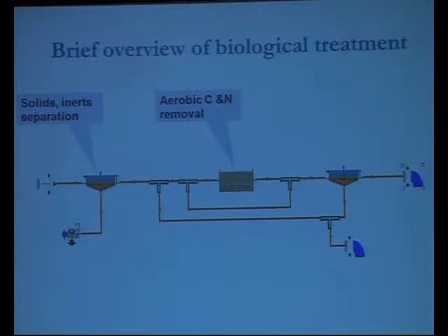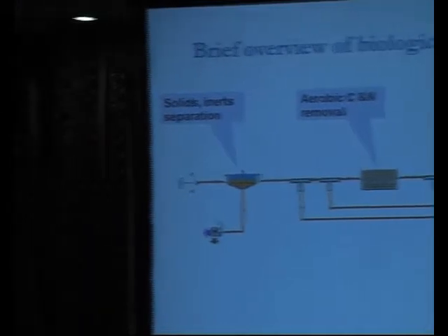Again, just to recall, when I say elemental approach for fecal sludge, it basically refers to the primary constituents. And from a broad perspective, it's carbon, nitrogen, and phosphorus. And just to again remind all of us, in what form is carbon present in fecal sludge or sewage or most of these streams? In terms of an oxidation state, for most of these streams, carbon is present in the oxidation state 0.